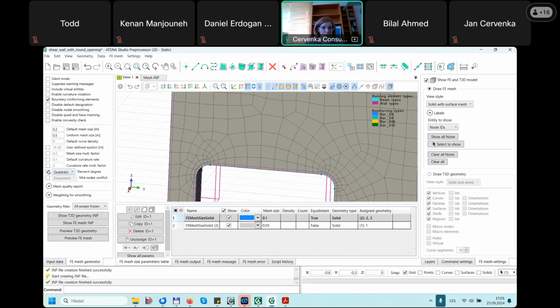If you have the global linear one and assign locally the quadratic one, it will be omitted. So if you are using even partially quadratic mesh, it should be globally quadratic, and the linear mesh should be assigned locally.